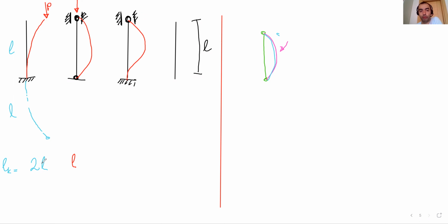So what I'm looking for here is a total curve like this. The total curve in this curved member is from here to here. So when we look here, the buckling length should be less than L. So it's 0.7 L.